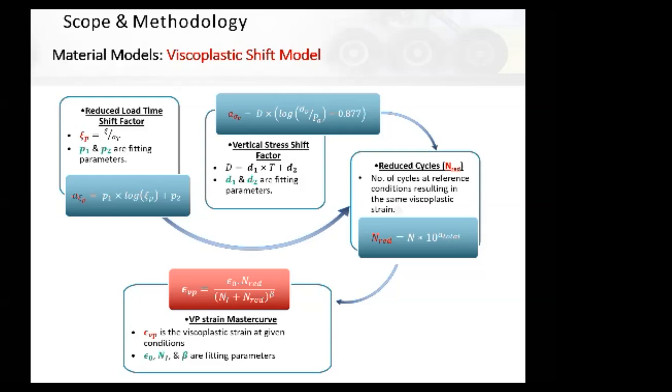And once you have these shift factors, you can combine them together to form one universal shift factor. That's why the model is called the shift model. And then once you have the overall shift factor, for any stress at any temperature, you can convert it to a reference stress at a reference temperature and predict the response for your input.